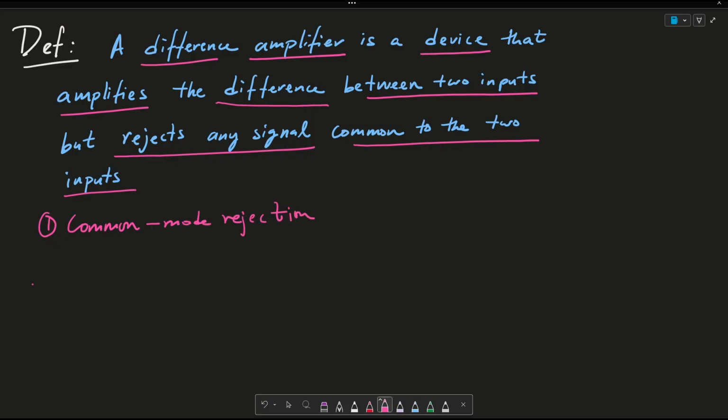Imagine we have a signal called V0 and we pass it through what's called a single-ended differential amplifier. And then we get what's called differential pairs on the right-hand side, V1 and V2, where V1 is a sinusoid and V2 is the inverse of that sinusoid.